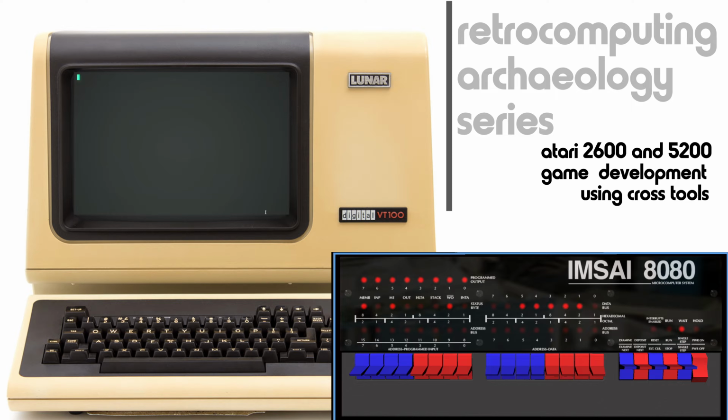And so the only thing I need to do right now to boot our cross-development environment is to flip the run stop switch. And that puts us immediately into our CP/M environment. At this point, we get a simple little sign-on message that informs us that we have a CP/M 2.2 machine that is set up for 54 kilobytes of transient RAM.